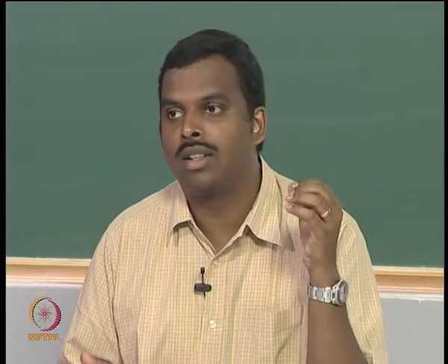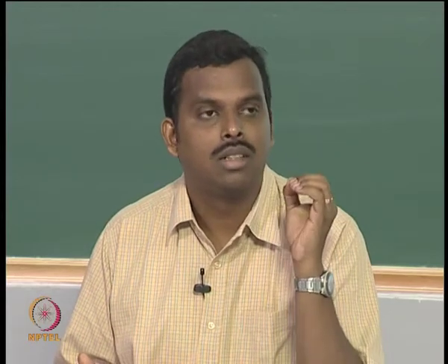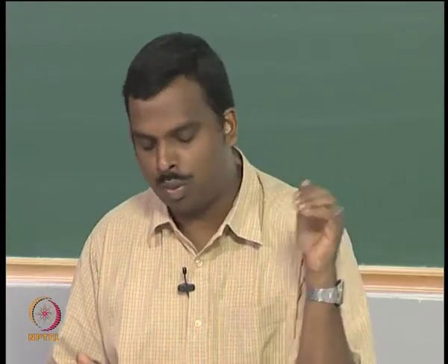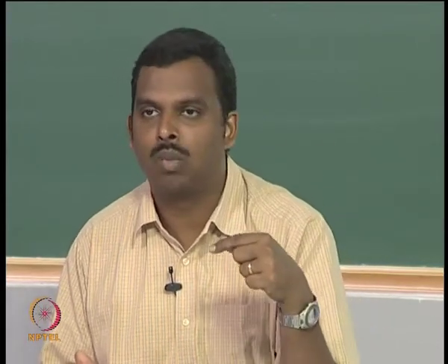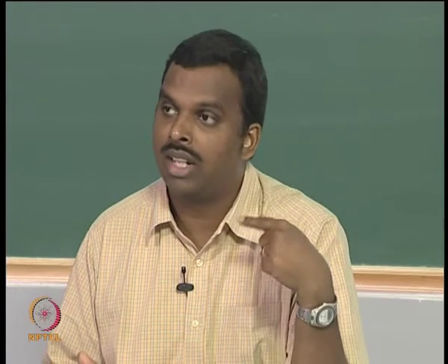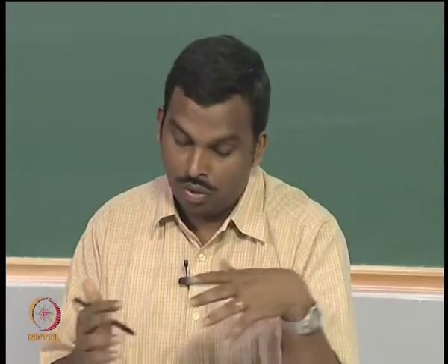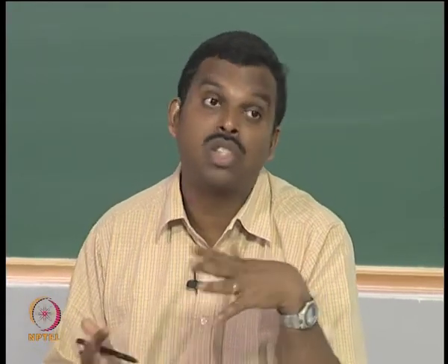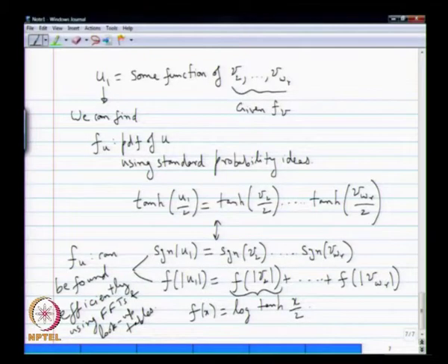Look at the definition of the threshold. How is threshold defined? It is the largest parameter for which the probability of error goes to 0. So you have to run density evolution several times till you keep finding that. In the numerical method for finding that, that is also 1000. So you are running this density evolution step thousands of times, maybe even millions of times. So you have to have a very efficient process for this, and FFT and lookup tables give you a pretty decent process.